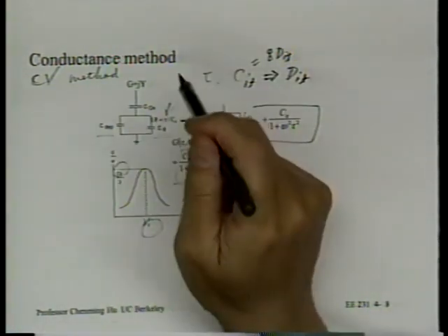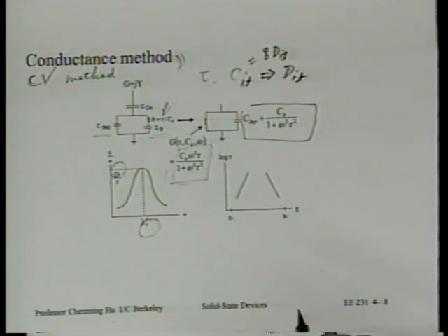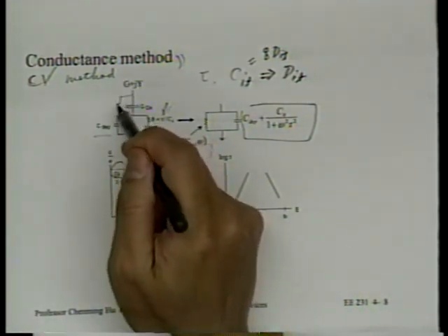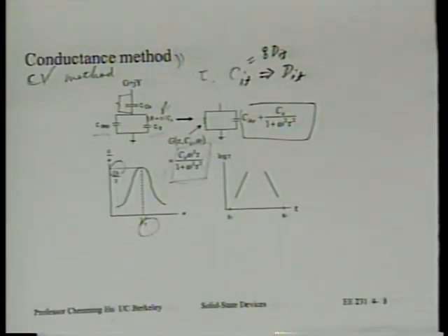In general, making capacitance measurements is becoming very difficult when the oxide is as thin as it is today, because there's a significant amount of leakage current. So even if we just want to measure the thickness of the gate dielectric from the CV measurement, we already encounter a lot of difficulty. And now trying to get information about interface traps is certainly difficult. So you will see that there has not been much work on characterizing interface traps in very thin dielectrics, let's say 20 angstrom or thinner.